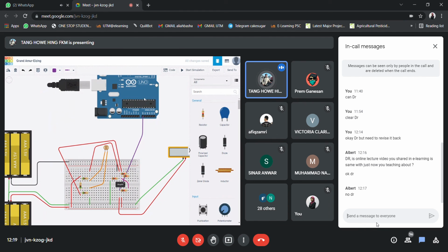Okay, this is A0. But you can see that once the current is output from the op-amp and then enters into the Arduino Uno, it cannot return back to the batteries over here. And there is a reason why we need to common ground this.